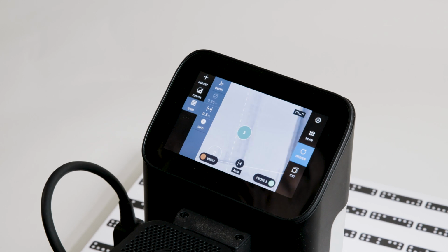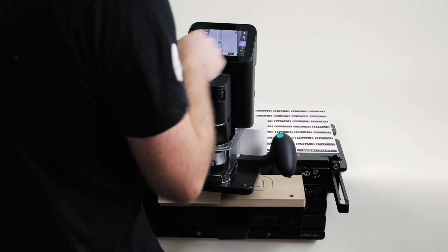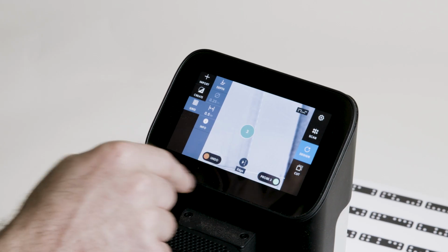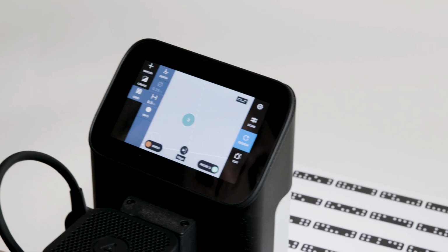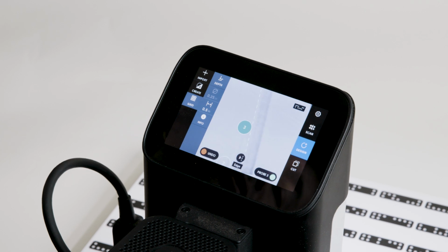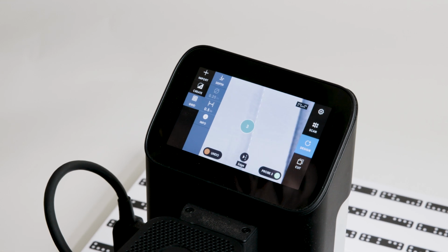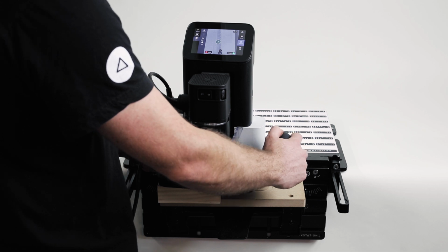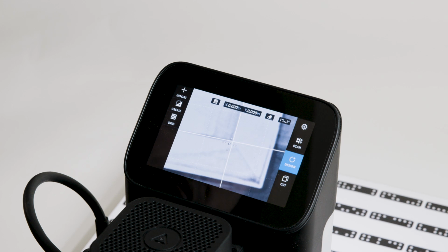Now, same thing happens. We're in auto mode here. It's assuming I'm probing on the left-hand side of the probe. I'm actually probing on the right, so I can override that as well. Centered, right. And once you override it, it remains locked. It doesn't try to automatically guess for you. So it should make things nice and quick for standard probes and leave the door open to adjusting for more non-standard probing arrangements. So probe the right-hand side, third probe, and now we have a grid aligned with this inside edge.